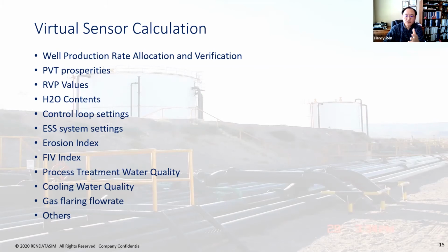And associated with this, since the solution is there and integrated, then you have all the PVT properties, and this is non-sparing. Okay, properties, RVP values, water content, control loop settings, and whether you should favor oil more, favor gas more, or put more to flaring, and what is the penalty for the flaring. All those things have to be considered as a whole, okay, not by silos.